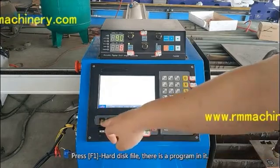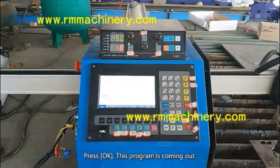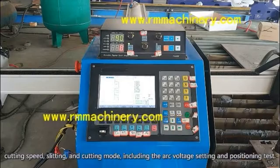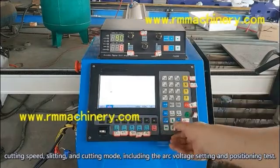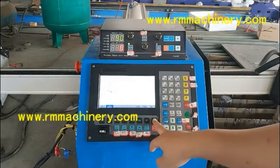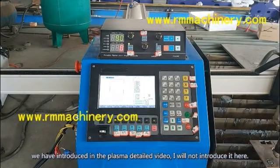Press F1 for hard disk files, and there is a program in it. Press OK, and this program comes out. Set these parameters after the picture is imported: cutting speed, slitting, and cutting mode, including the arc voltage setting and positioning test. We have introduced this in the plasma detailed video, so I will not introduce it here.